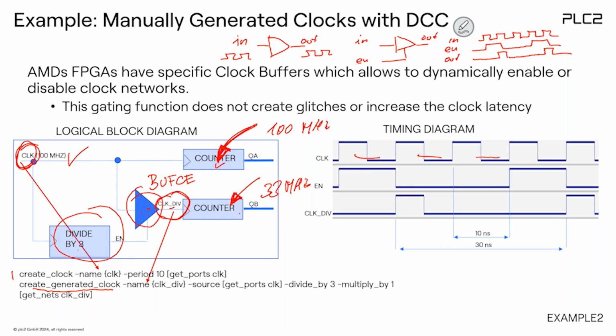So this makes it very, very easy. Let's assume the counter might be, I don't know, a 16-bit counter, which can easily run with 100 megahertz. But this counter, let's make it 100-bit. Okay, so this 100-bit counter, a standard binary counter without any tricks, will not run with 100 megahertz. But maybe you don't need it to run with 100 megahertz. You don't need this high resolution. You need 100 bits, but you don't need the resolution.